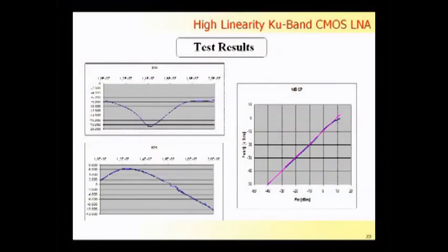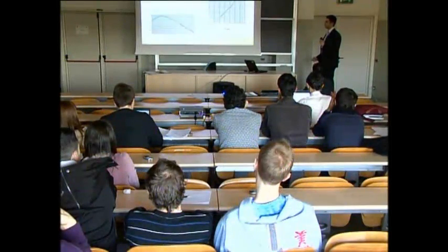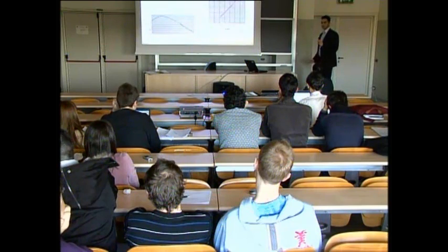Here is also the S21, the gain of the system, that is less than the one simulated. It is not around 10, 12, but around 6, 7, and it is not at 15 but centered around 12. This is because of the inductor model that we have used, an ST library model, and ST made its model wrong.